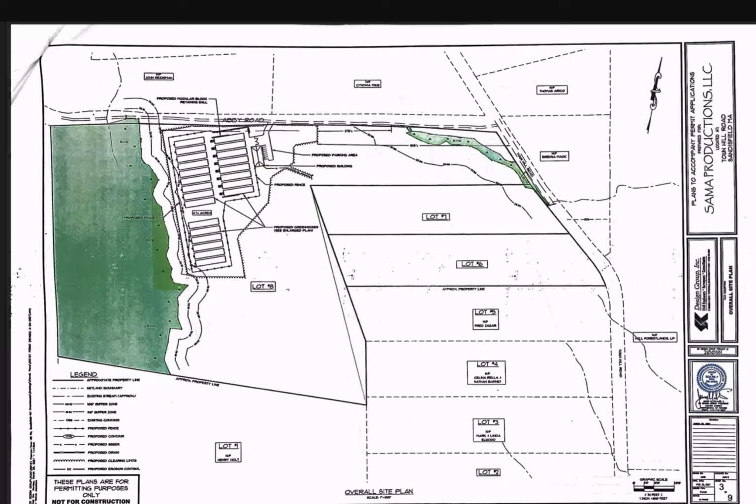And in doing that, it still comes out to about, honestly, 15, one trip per employee. So you're talking 15 to 20, even 20 trips. Your house generates 7 to 10 trips, to give you a place to anchor yourself. If you said 7 to 10 trips for a house on 46 acres, and if you had frontage on Abbey Road, you could fit 4 or 5 houses at this location by right.